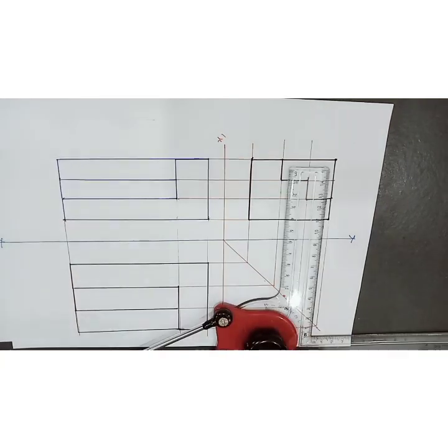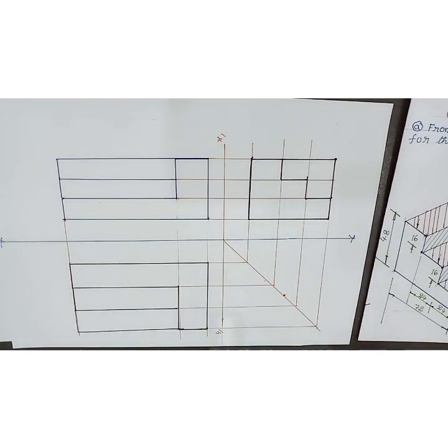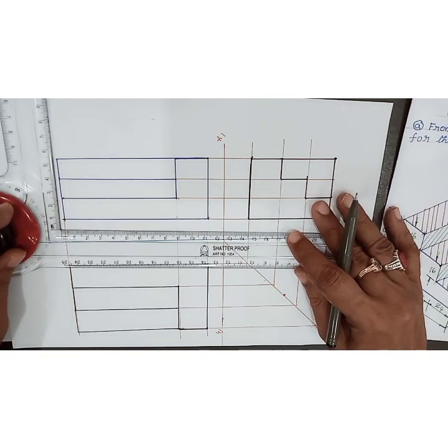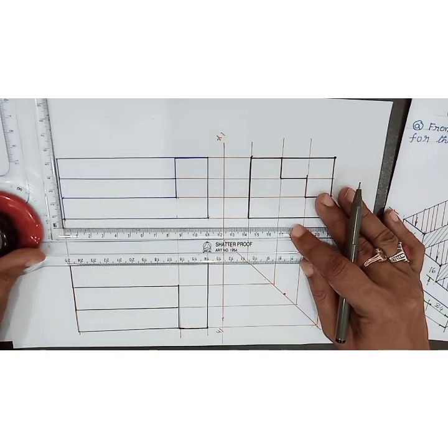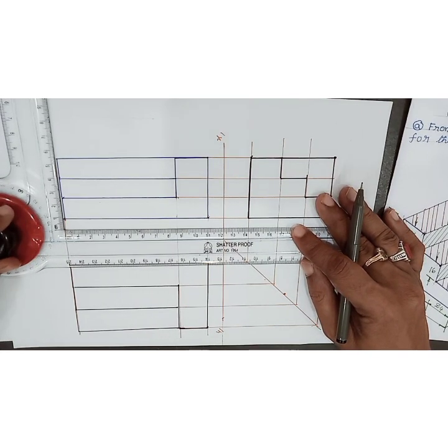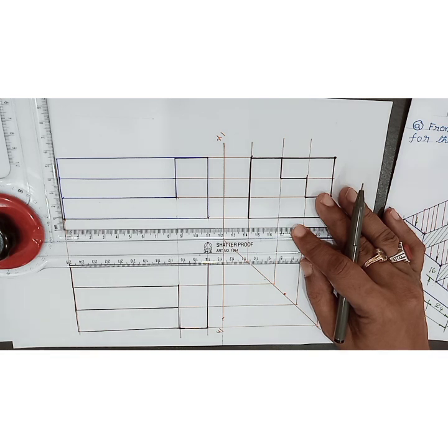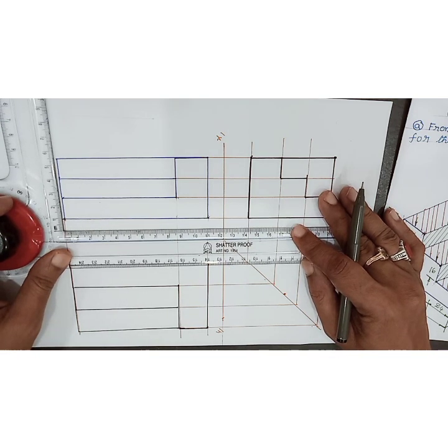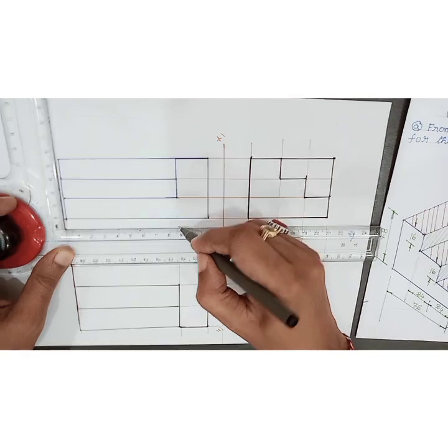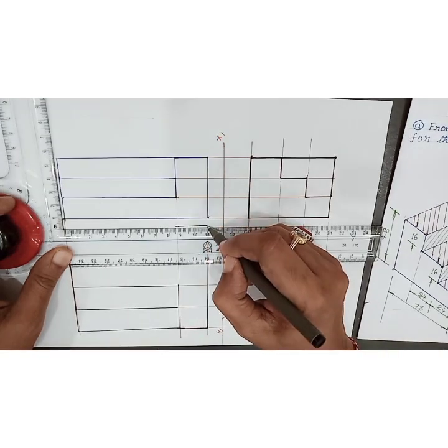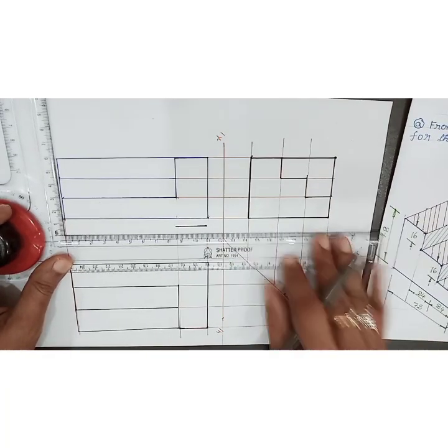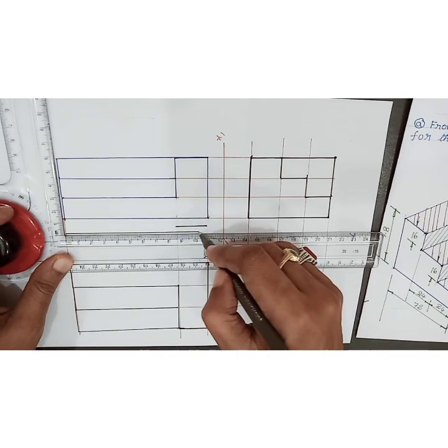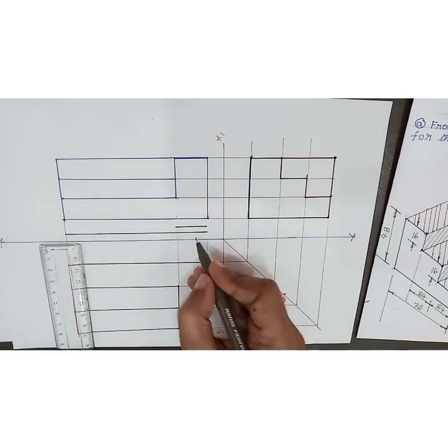After drawing the front view, top view and side view, we have to do the dimensioning. Generally in the case of dimensioning, if a length is shown in the front view, then there is no need to show that particular length in the top view. That is, dimensioning should not be repeated. Say here 24, 104.